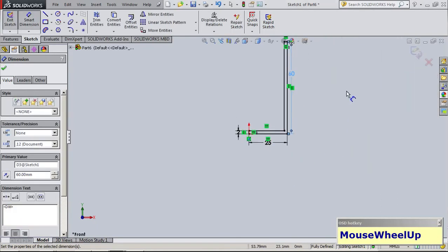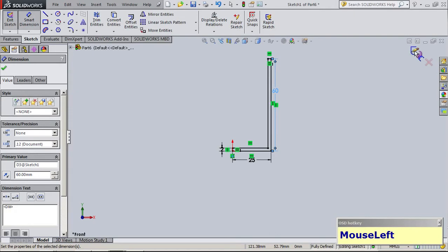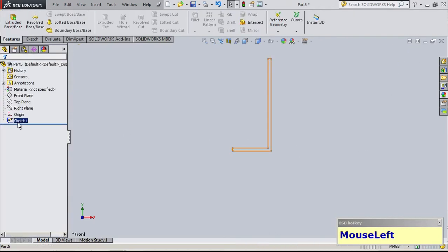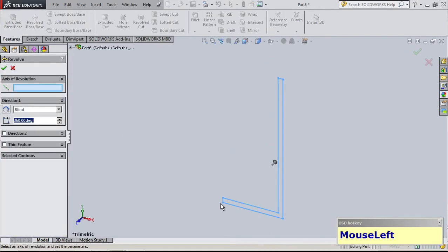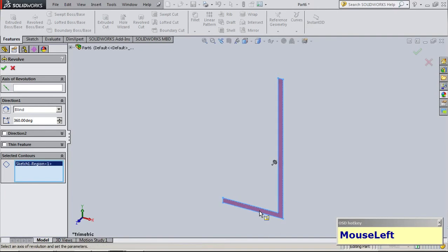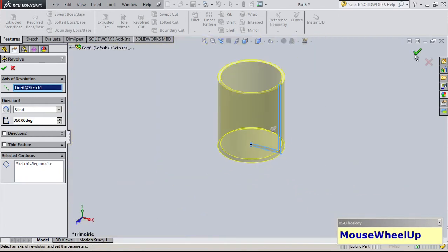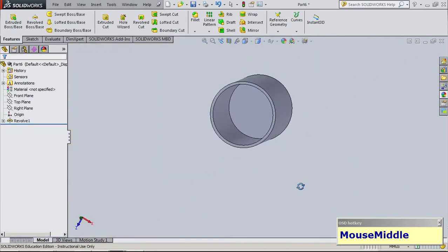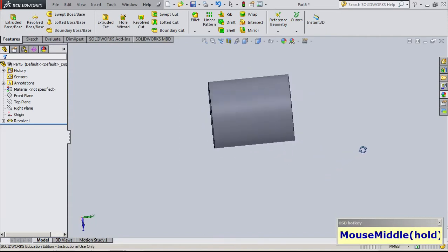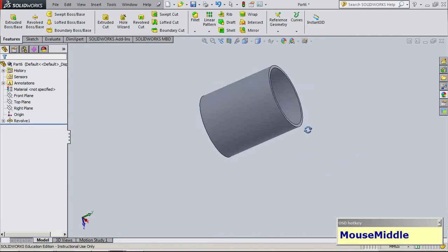Right, scroll out and then say OK. Now I'm going to select my sketch, revolve, and then since this is already selected, the sketch, I'm going to select the axis. Actually, sketch wasn't selected, I lied. Select this. For the axis, I can basically select this particular shape and then say OK, and then this basically creates my mug, except that these edges are a little bit sharp.